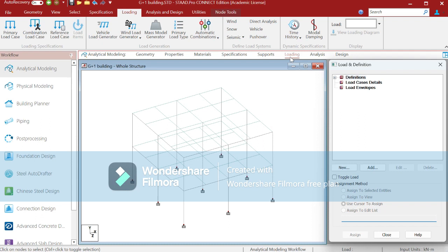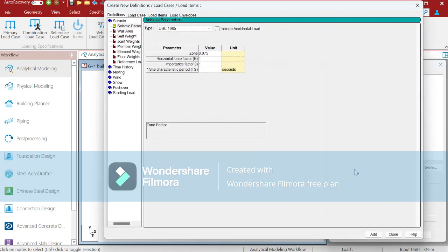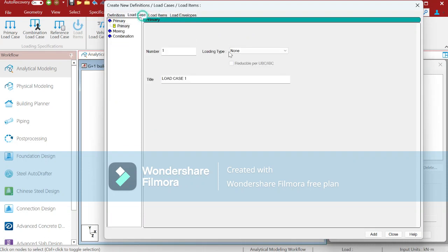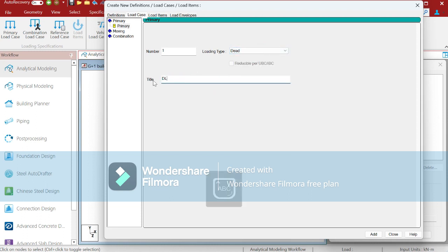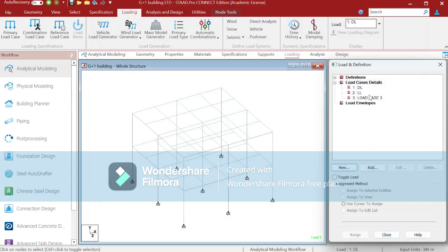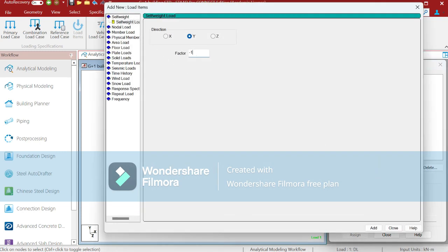Now we will go to our loading portions, load case details. We will give three types of loads, that is wall load, floor load, then dead load and live load. You can see on your screen how the load details and values are input. I think that is self-explanatory. Here we have taken dead load, live load, floor load and wall load, but as per your requirement you can take earthquake load also, wind load, snow load, various other types of loads are there.